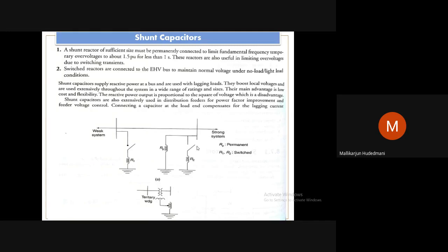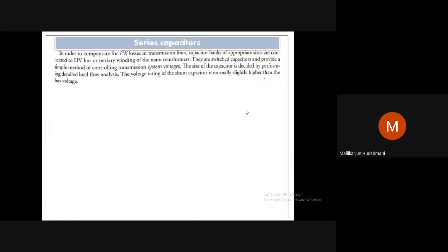Whenever overcompensation has been seen or load removal has come, to compensate that state of the system, these switches need to be closed in a systematic way. This way, shunt capacitors and shunt inductors are very important in managing the required reactive power, as per the required injection as well as absorption, to maintain the voltage profile of the system under control.